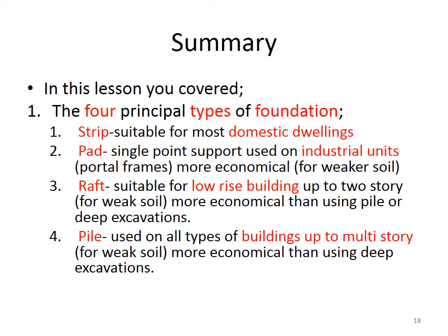So summary, in this lesson you covered the 4 principal types of foundation. One was a strip foundation, which is suitable for most domestic dwellings, probably the only type of foundation you'll come across. Number 2, the pad foundation, which is a single point support used on industrial units or portal frames, and again this might be more economical and used on weaker soil.